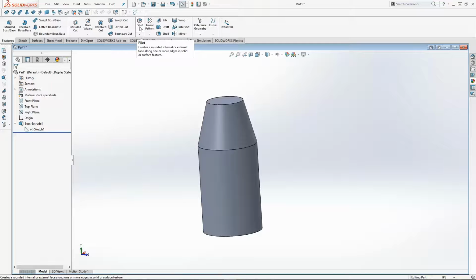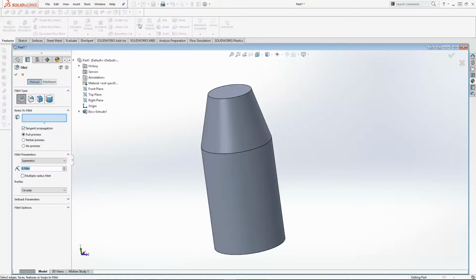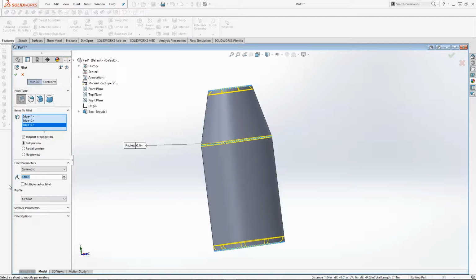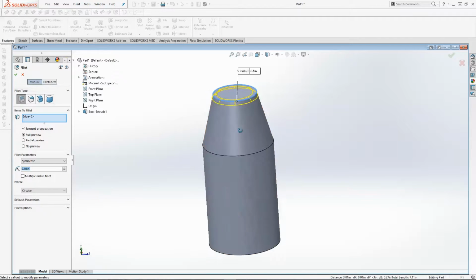The next step is to create a kind of a contour shape. This one right here. It's in the Features tab. Go ahead and click the fillet and click that circle. And you can click any vertex you'd like. If you click multiple, you'll be able to fillet all of them with the same radius here. But we'll actually do the top to show you some features.